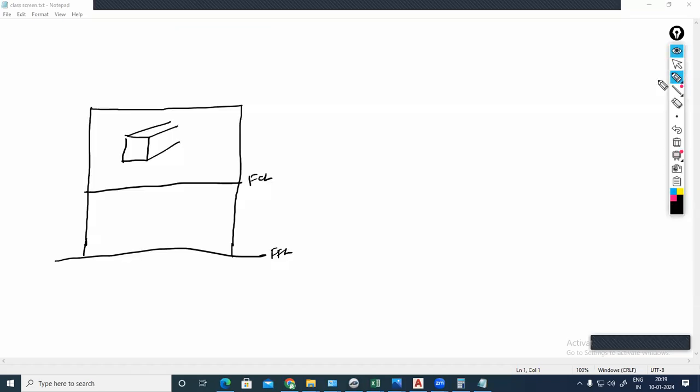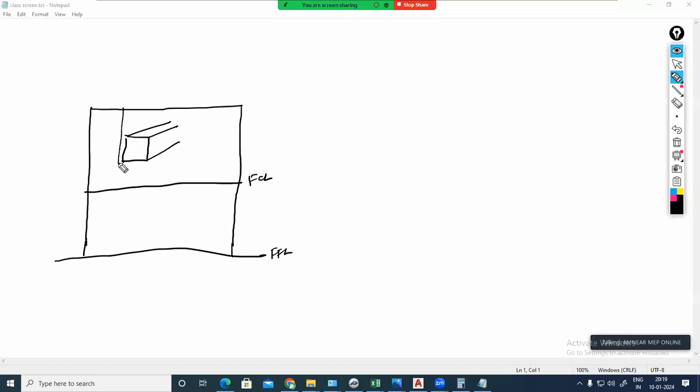Okay. Duct, I should provide a hanging allowance. Normally, ducts will be hanging only, no? We will be hanging like this. So this is my bottom of slab, and this will be the top of duct surface, and this will be the bottom of duct. If you are having insulation, then top of insulation, bottom of insulation, like that it can come. This is without insulation. This is my top of duct. So this one is the hanging allowance.